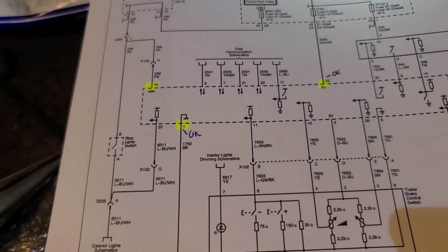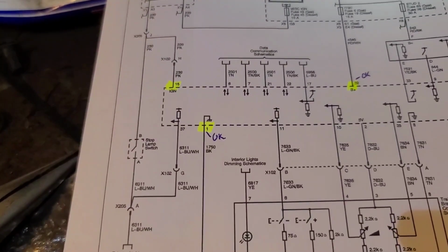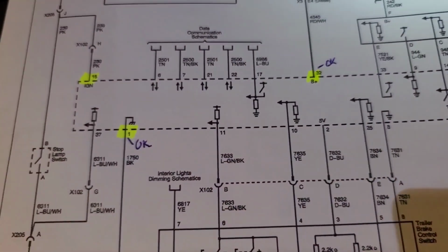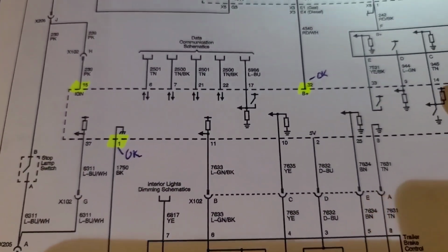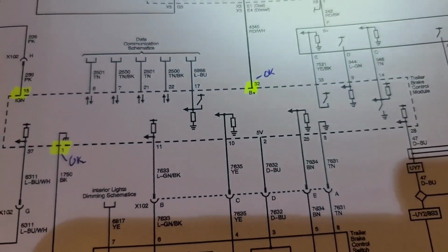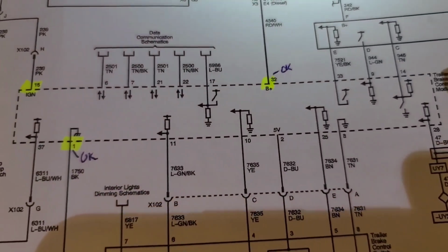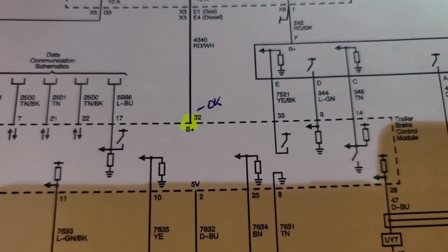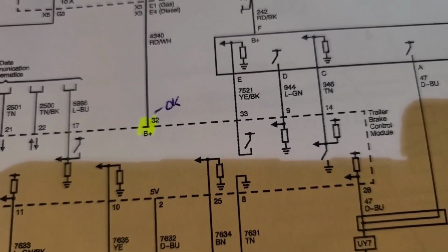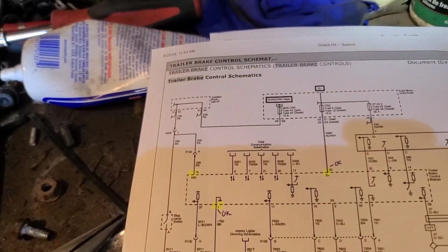I've got the controller disconnected, so I'm going to jump power to pins C and see if it lights that headlight, or this test light on pin 14. I can't see the numbers. I got to get stronger glasses. 14, 8, or 9, and got to look at the camera to see it. 33. 14, 9, and 33. So we'll check continuity of those wires.